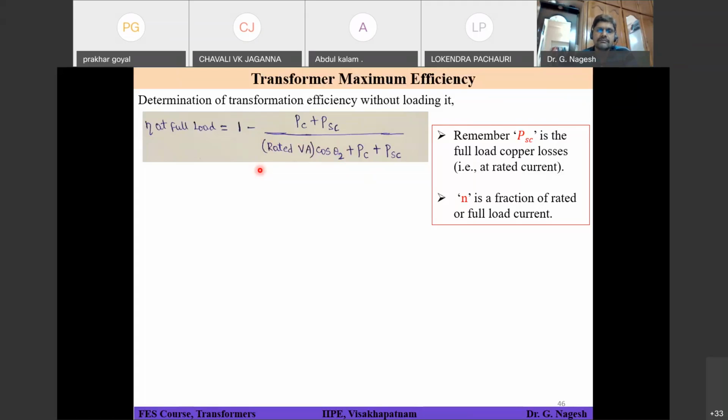After some time 2 motors may be shut down, so there are only 8 motors running on the transformer. So your secondary current is not the rated current, it has come down because the number of motors running is reduced. So the load current on the secondary side is not in your control, it varies based on the instruments connected on the secondary side.